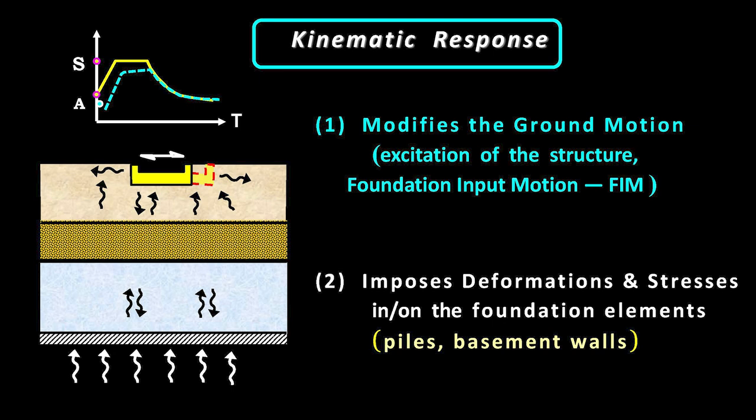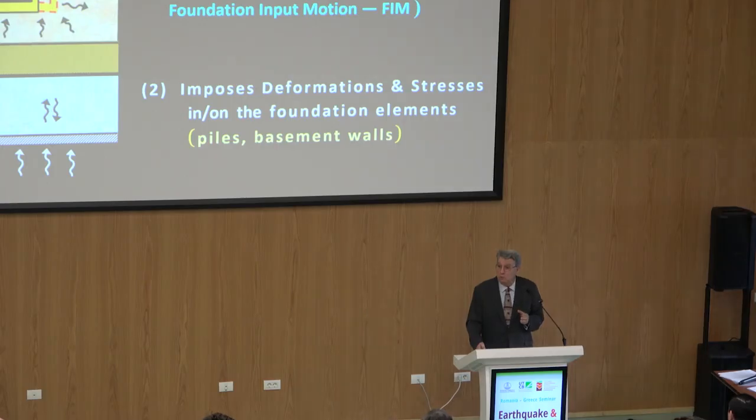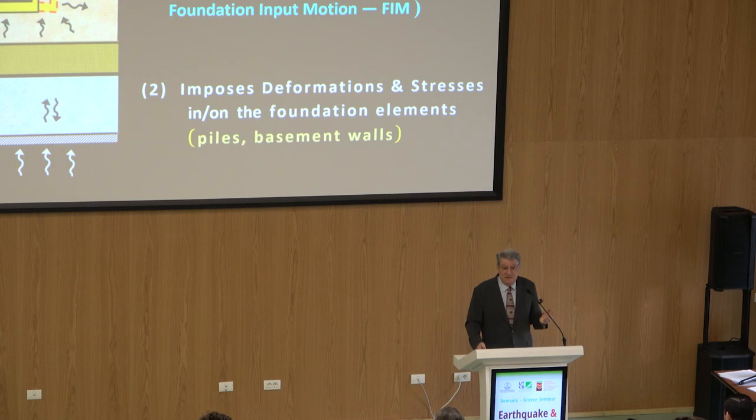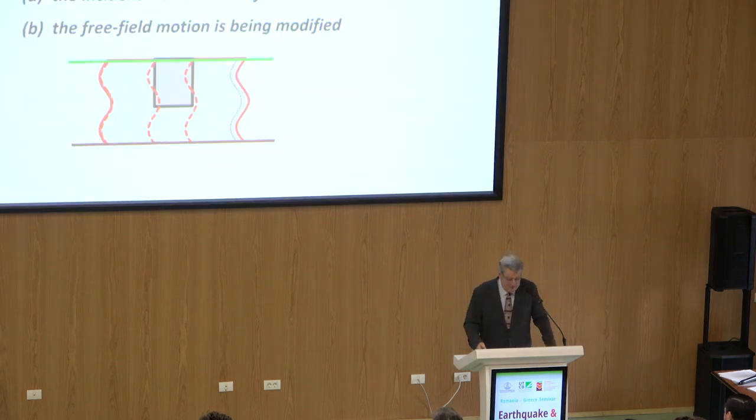And also, these embedded foundations, unfortunately, they have to pay something for this. They will be subjected to additional distress, especially piles and basement walls, or simply retaining walls. Actually, the basement walls and retaining walls are designed for kinematic effects, not from the load from the superstructure, which they usually do not carry. Anyway, have this in mind.